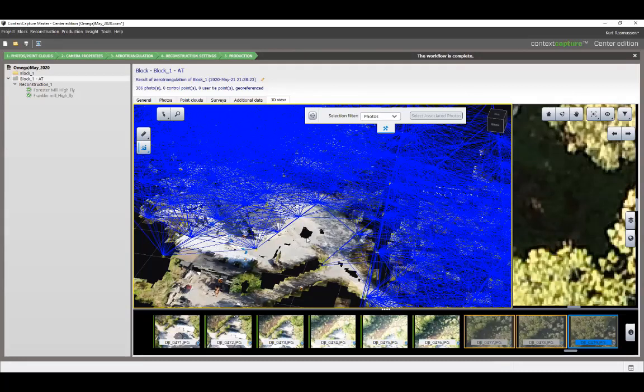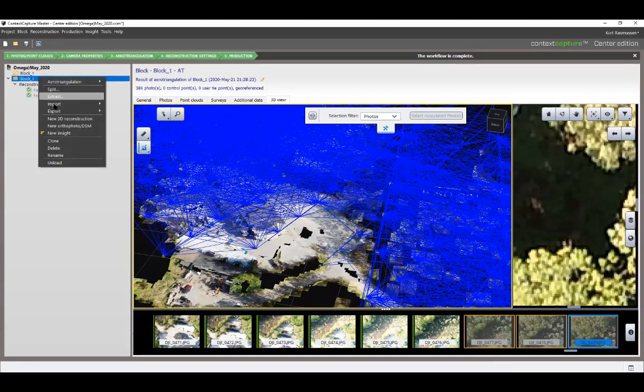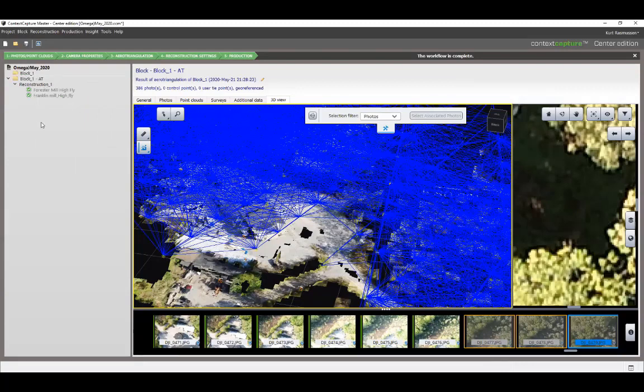The whole key to that is making sure you're in the same coordinate system. So I tell people, if you're going to be doing ground stuff, whether it's photos or LiDAR, have your targets there that your aerial stuff is seeing as well at the same time. And then we can lock both in that world. Then you select that and right click, and there's an option that comes up that says merge. You would have your photo one, your LiDAR one, you'd merge them together and create a beautiful model.